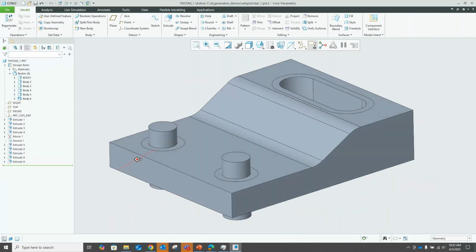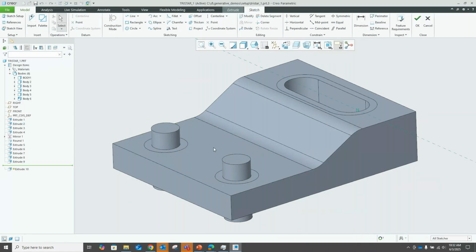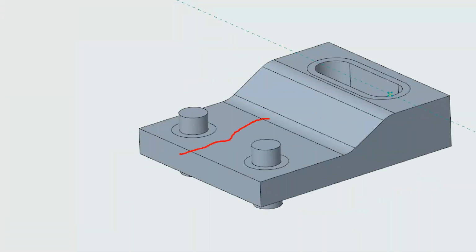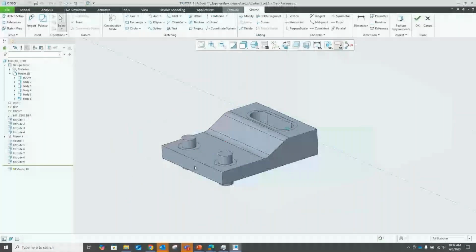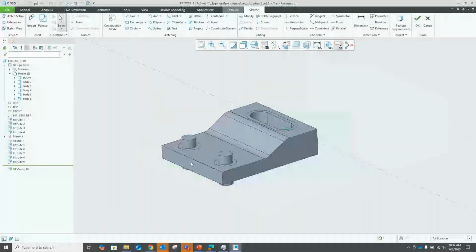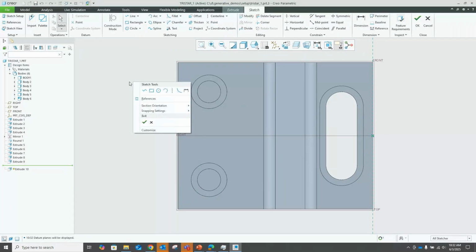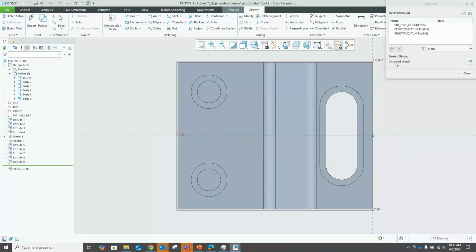So one other body that I could potentially add, maybe that could have been part of the original design, but maybe I want you to work around this area. I don't want anything to happen in that area. It's kind of like an exclude area, right? What I could do is sketch, maybe we'll go to references and grab this as a reference for now.